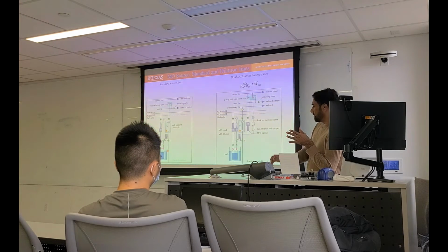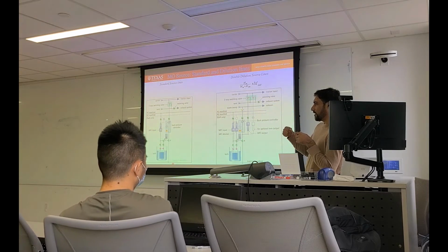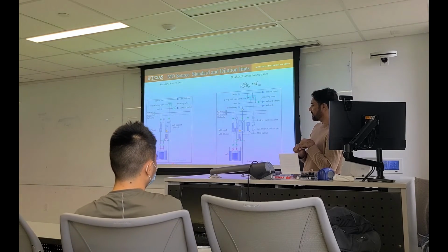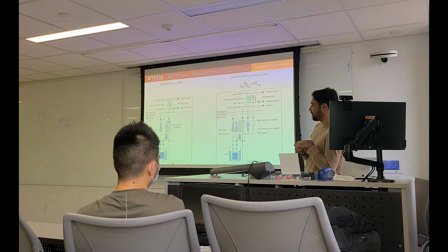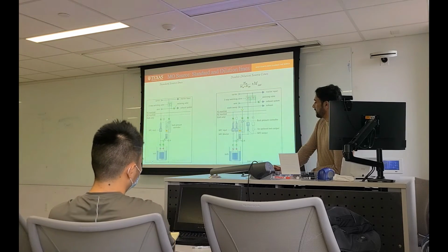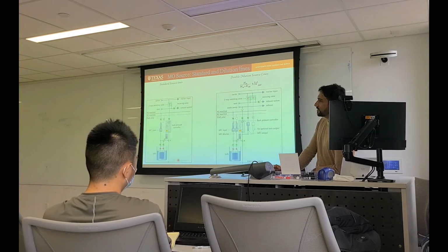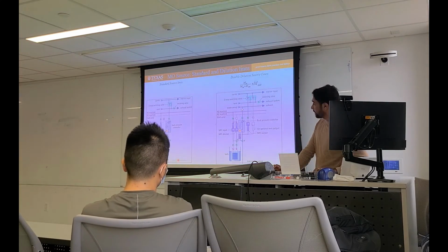And if there is a leak, because this vacuum pump is sucking, if the helium is going to the point where is the leak, then the pressure of the vacuum pump will drop, and the vacuum will be dropped. So in that case, you will figure out there is a leak. So there is additional line with any source, with any line, to connect to your vacuum pump just for the leak test. Yeah.